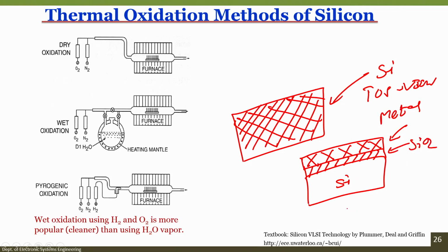If I show you that you use this chip for EEG measurement or for other measurements, you will ask a question, what exactly is the substrate? We say silicon. Then the question is how silicon is fabricated. That is why we took the class on silicon fabrication. The next question is if I want to have insulating material between silicon and metal, what kind of insulating material can I use. So, we are discussing silicon dioxide and its growth process.